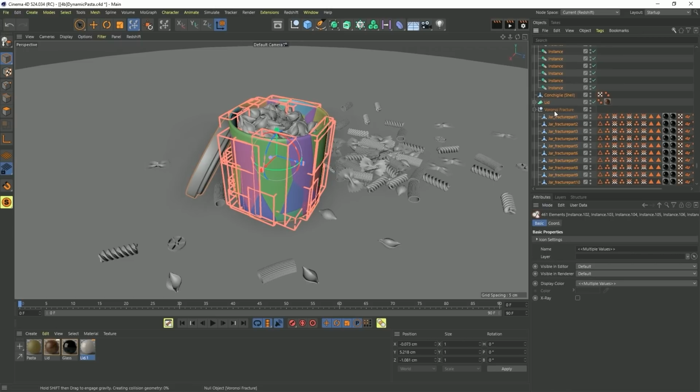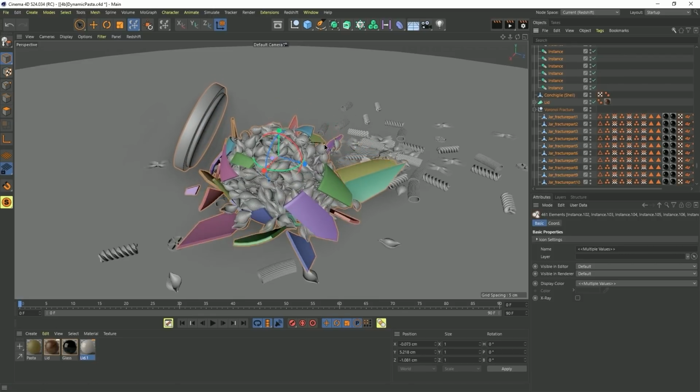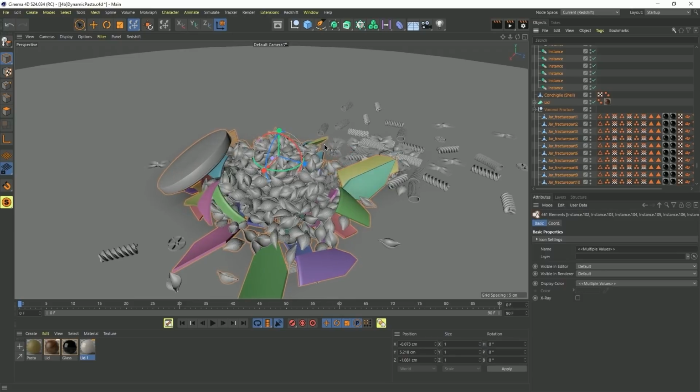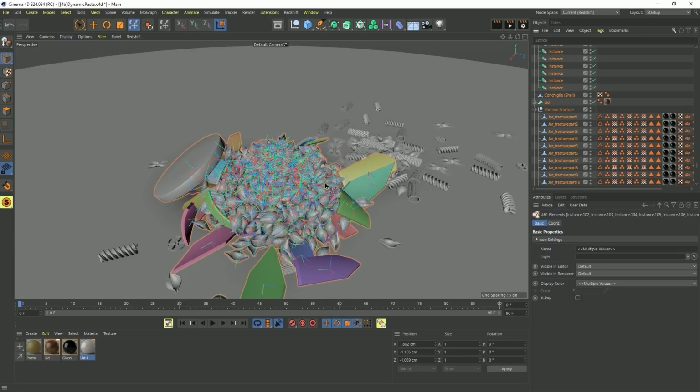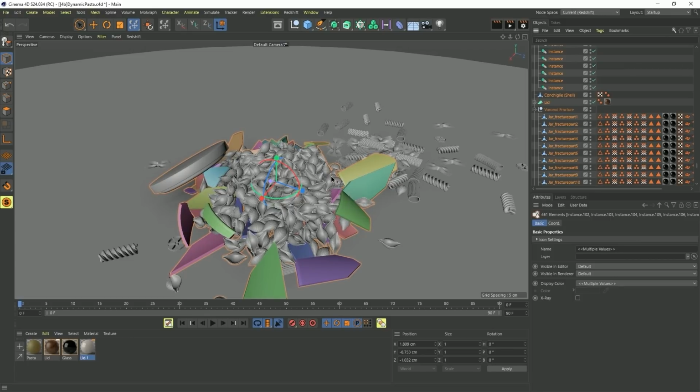So deselecting that one, I can hold down Shift and drag, and you can see the calculations wrapping up. The entire thing will shatter and fall to the ground and settle in. As it gets to a more finalized state, I often let go. So it's like, okay, that's kind of locked in, and now more gently let them settle in. It just gives you an undo state if you want to.